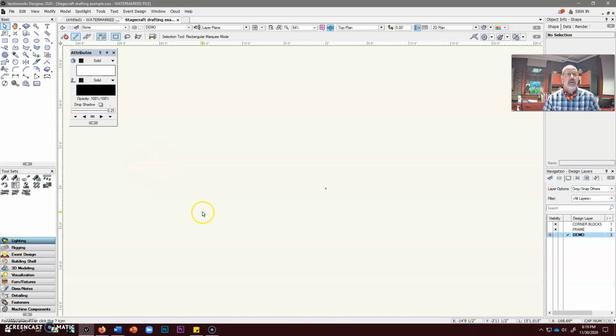All right, so let's use our single line tool. Notice now that my contextual menu on this ribbon has changed. I can constrain the line to rigid 90, 45, 30 degree angles, or I can draw as I normally do with an unconstrained line that I can then constrain by holding down the Shift key. Right? I can draw wherever I want to here, or I can hold the Shift key down and make it snap to various degrees.